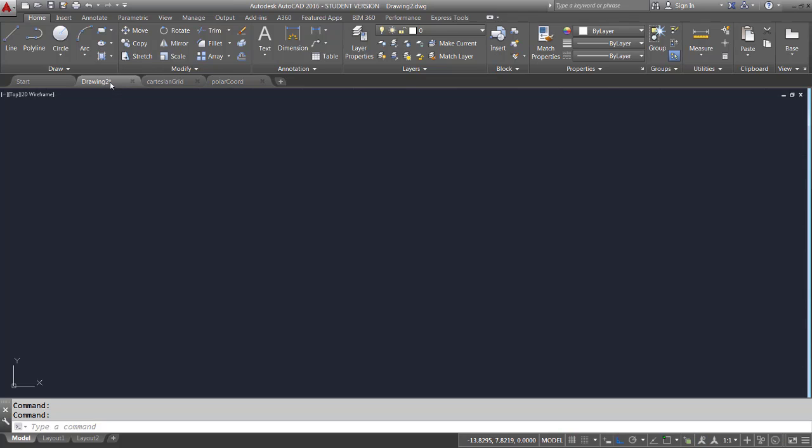So if I go back to my drawing, we got out of our command. That's okay, because as I was moving around on the tabs up top there, it canceled my command. So all I have to do is type in L, enter, and the line command starts again, 0, 0, enter. And now as I'm dragging along this distance, as we said before, we see the readout, and I can put in a distance. So let's say I put in 30. And the line now becomes 30 units long, or in this case 30 inches, and stops.